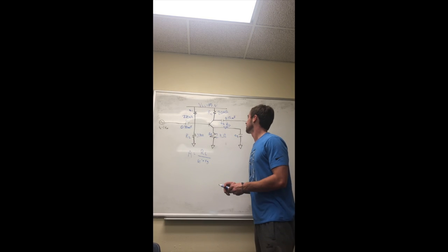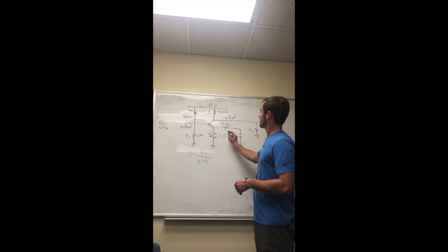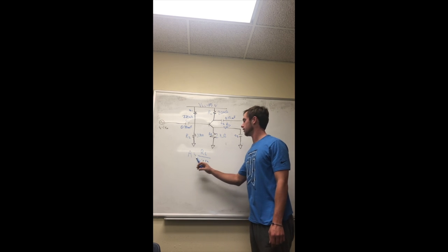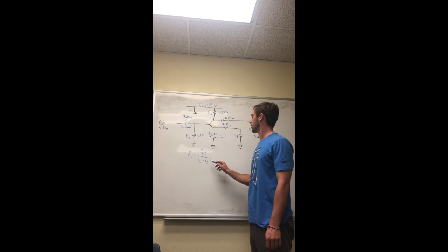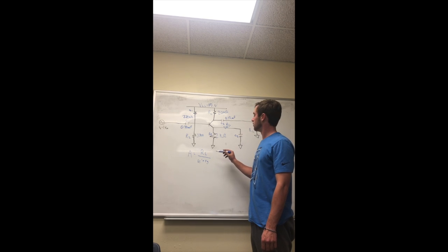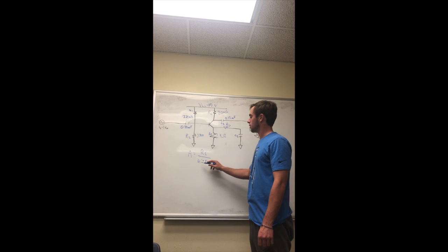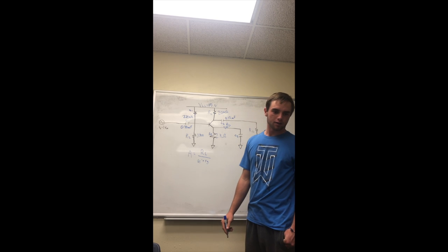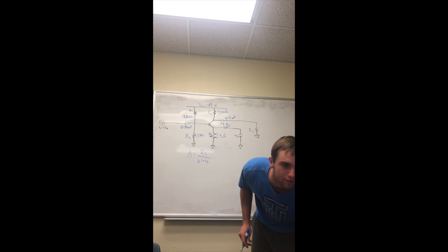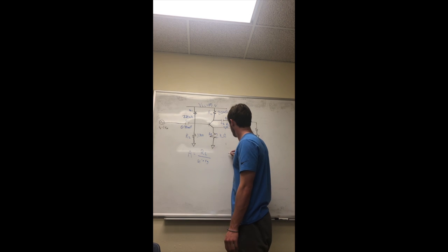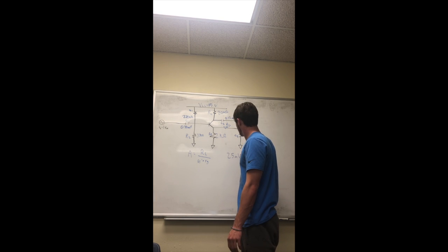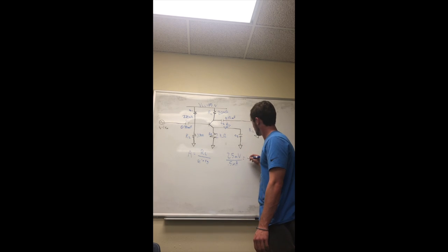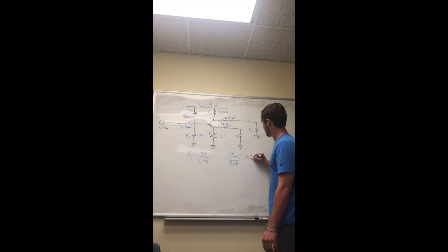microfarad. So now, to maximize our gain, we're going to add in a resistor here, RG. An equation that we can use to find RG is A equals RC over RE prime plus RG. We know RC is 20K. We don't know RE prime. And to solve for RE prime, you have 25 millivolts over 0.5 milliamps, which is our current, and that equals 50 ohms.